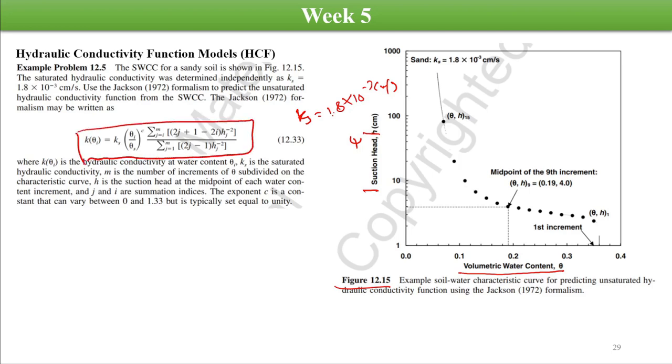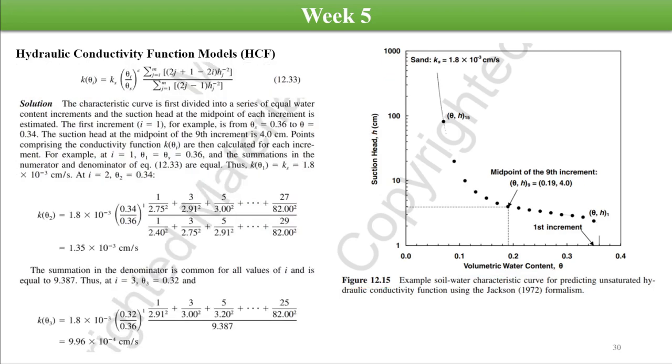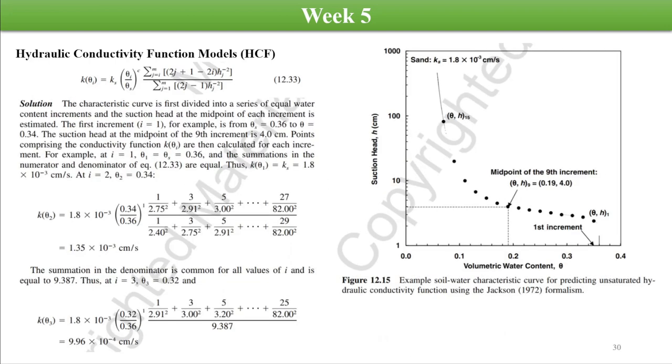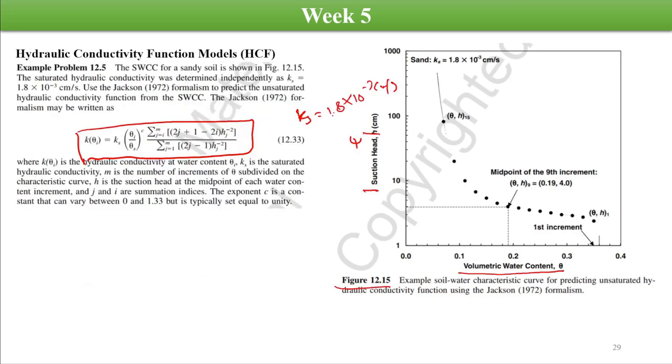In this formula, what we need to do is take small increments, and in these increments we need to calculate the suction heads. Based on these suction heads, we can calculate the hydraulic conductivity, right? So we'll see in a while how we'll do it.